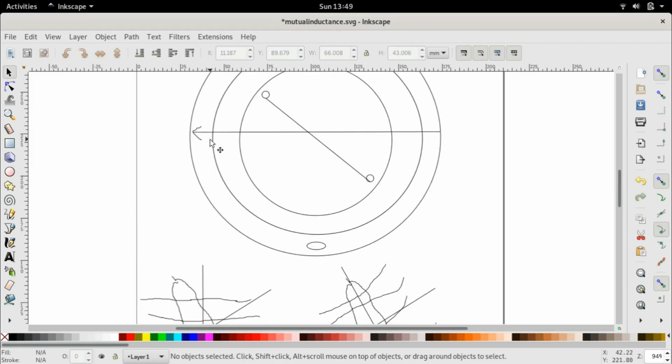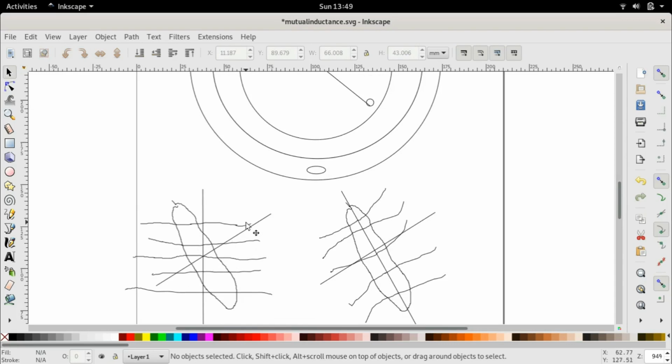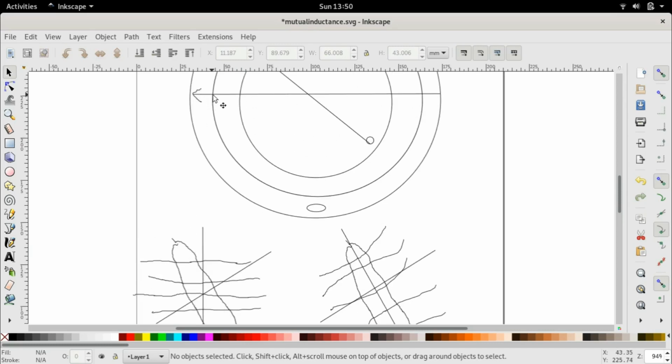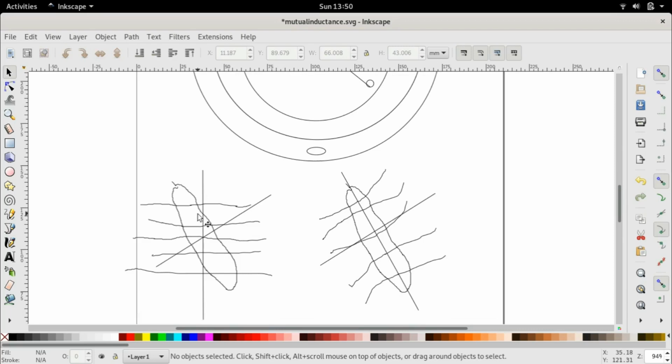And therefore, if we say that the stator flux is horizontal, but the rotor would have produced another flux, then in that case, we know that the stator flux that links with the rotor will not be exactly equal, will not be 100%. If this rotor flux were exactly aligned to the stator flux, then we can say that the linkage between the stator flux and the rotor is maximum. If the stator flux was 90 degrees to the rotor flux, then the linkage between the stator flux and the rotor is minimum. Whereas in this case, we now have something in between.